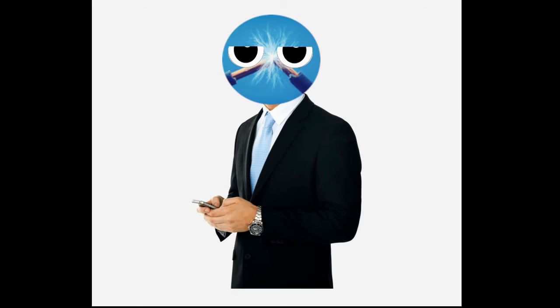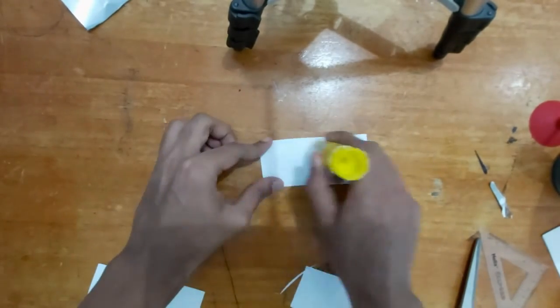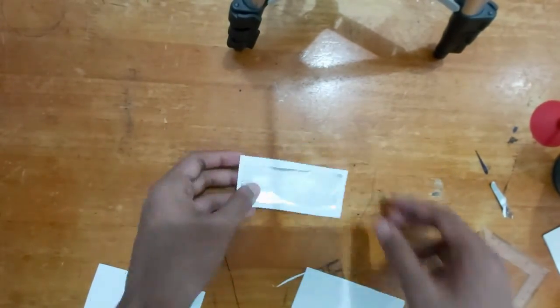Okay, I'm back. So to make your own capacitor, you'll need three items: some paper, some aluminum foil, and some wires for connecting. So firstly, you're gonna glue two aluminum sheets on both sides of a piece of paper.